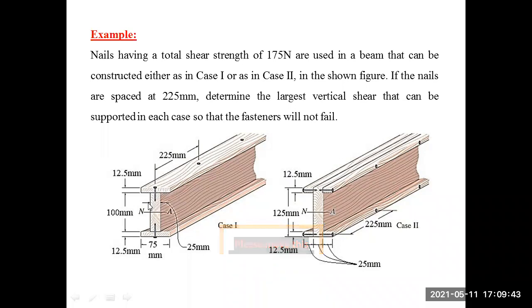If you have no screw and you apply a force on this I-beam, then this upper side, the flange, would have this relative motion, and it would get disintegrated from the web.